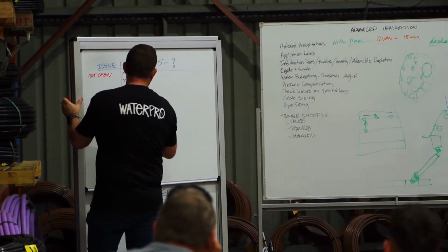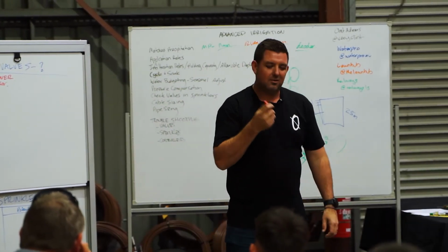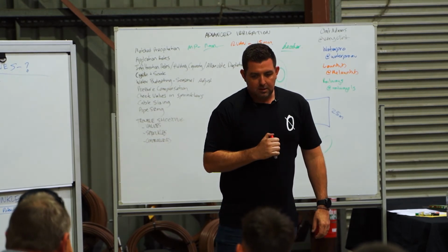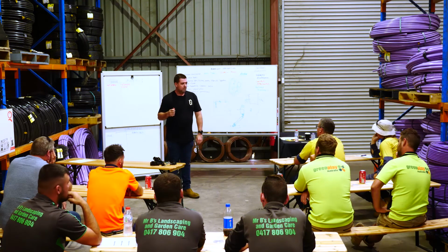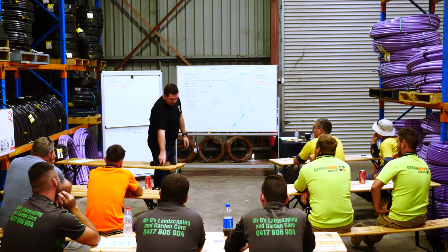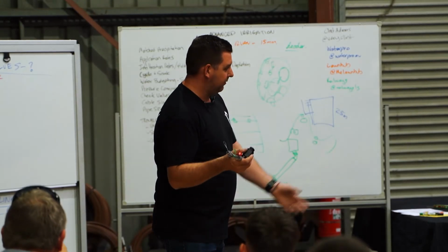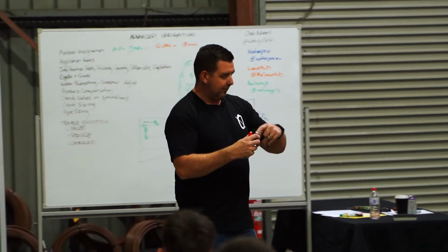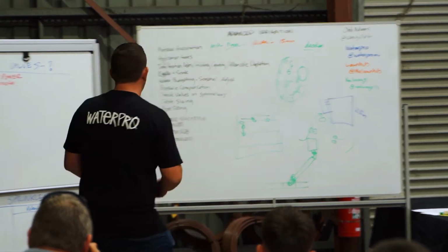Anything else you guys can think of that might stop a solenoid valve from opening? I'll give you this one because it could take a while. Debris. So it kind of crosses the water path. It's debris, it's stuck on, not off. Yeah, that's right. If there's debris affecting the coil from doing its job, so if you think about the hole that has to have the thing lift, if something's on there, it might not open. It's very unlikely that it's going to be debris, but it is something to look at.